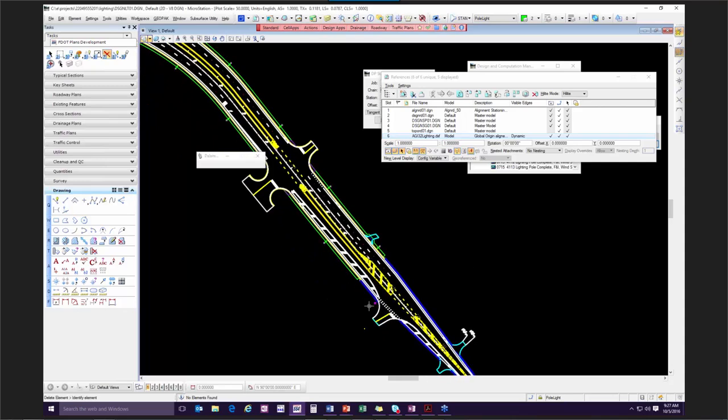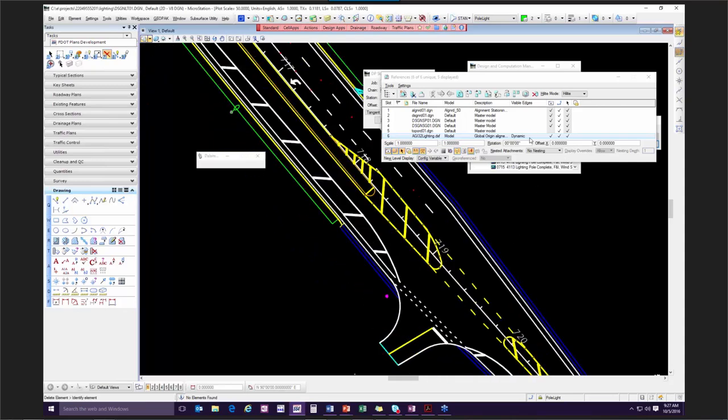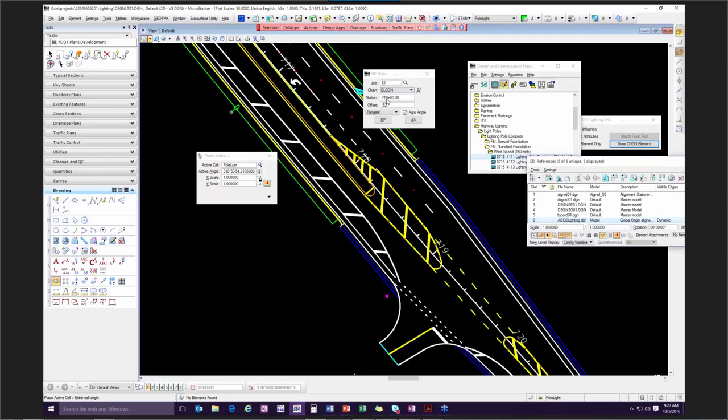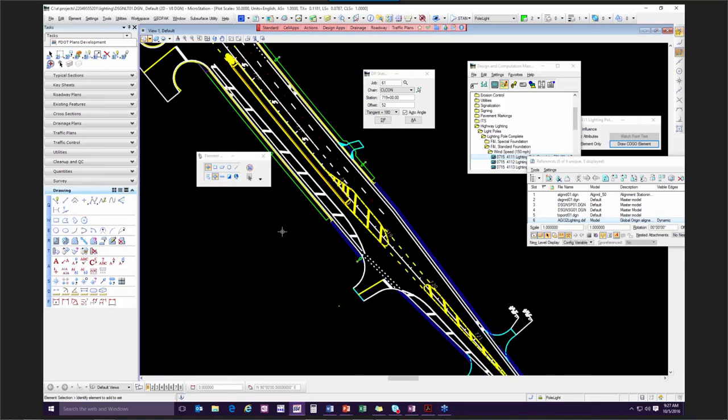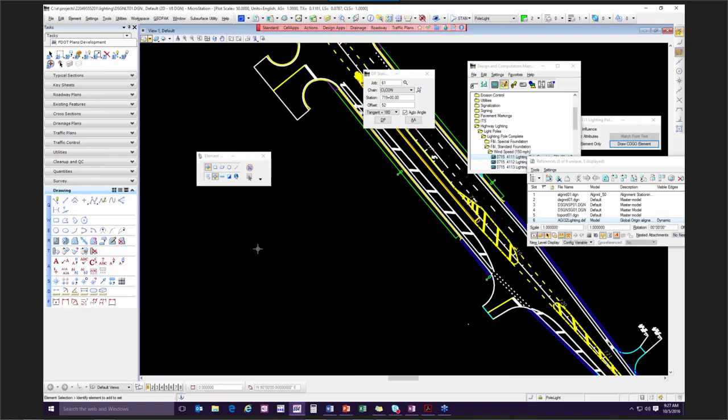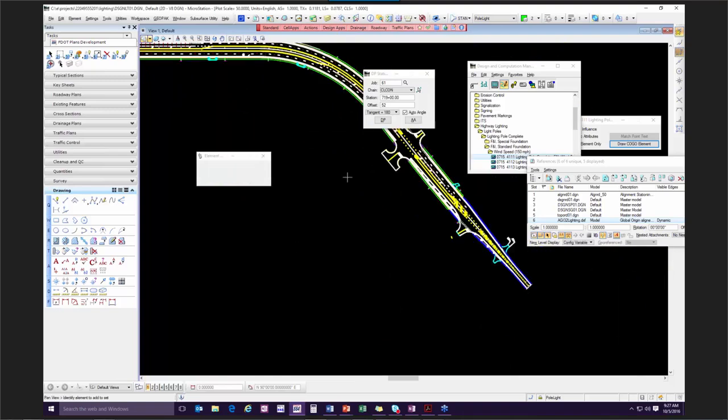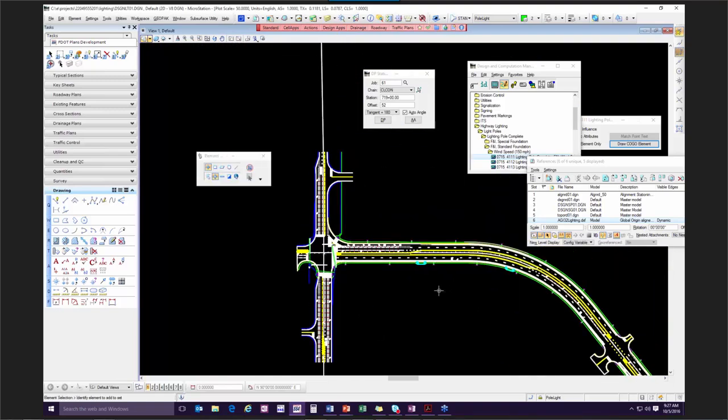And oh, I missed one. So it's real easy to see if you've missed anything. I'm going to go to my cell again, just real quick. Put one in here. That's 719, and it's at 52, and plus 180, data point, and now I have that pole. So now that's an easy, quick look. Did I get all the poles according to the design? Yes, I did. Okay. So that took us through exercises 9.1, 9.2, and 9.3.